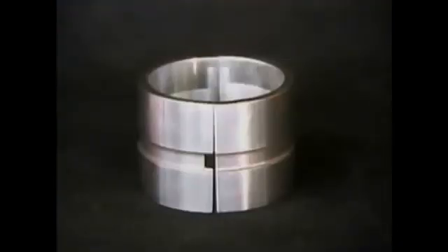Two types of bearings used by most compressors are radial bearings and thrust bearings. Radial bearings support the compressor shaft. The bearings are lubricated to allow the shaft to rotate freely inside the casing. But the bearings prevent most radial movement, which is movement that's perpendicular to the shaft.